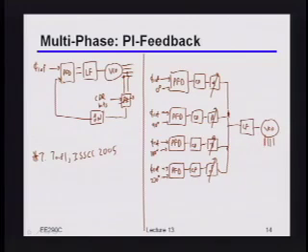So on one phase you fed it the 0 degree, and next time you fed it 90 degree, and you dithered between them. Is that what you're suggesting? No, what I'm saying is you have 4 feedbacks to the PFD, so have them at different counters. Yeah, but I think that's basically 4 separate dividers.